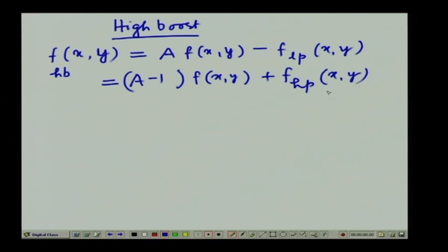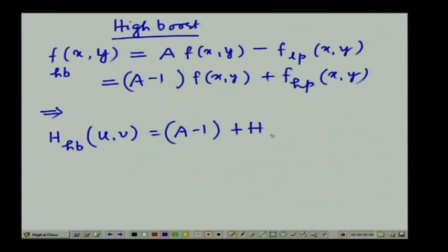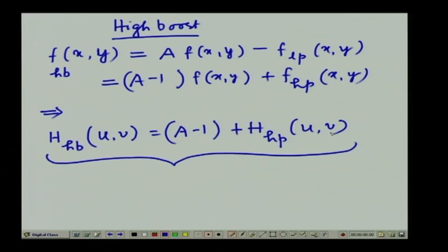In the frequency domain, the corresponding filter can be represented by H_hb(u,v) is equal to (A minus 1) plus H_hp(u,v). So, this is the high boost filter response in the frequency domain.